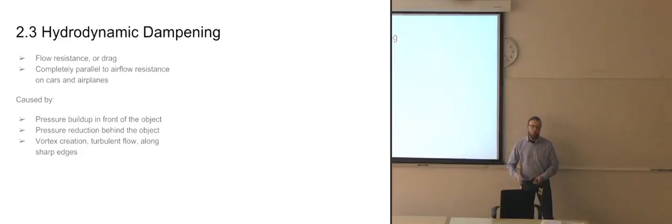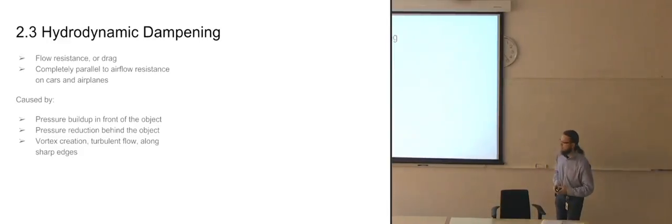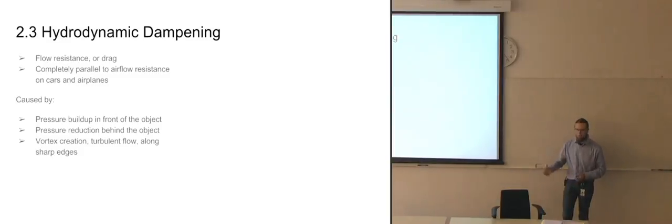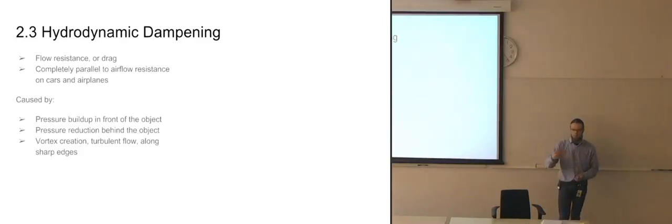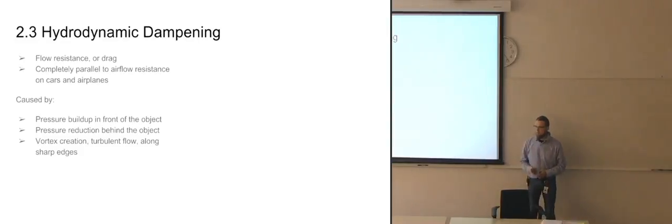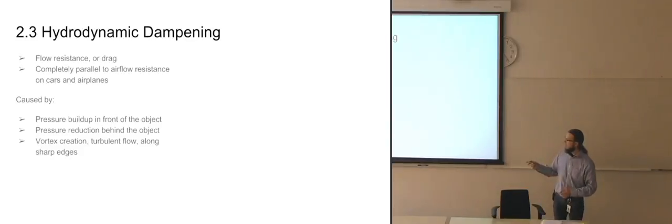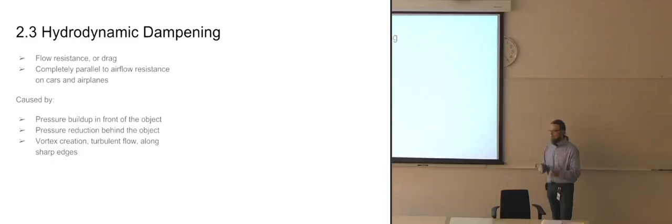If we had been able to do that, we would be able to make quite a lot of improvements on any gear that uses flow rates. So any piping, valves in hydraulics, anything that utilizes flow would have great improvements if we knew how to calculate this. We know how to calculate it as long as it's a laminar flow. That's not a problem. Then we can calculate it pretty accurately. But as soon as it turns turbulent, we have troubles. We can do approximations based on lab results and experiments, but we can't do exact calculations.